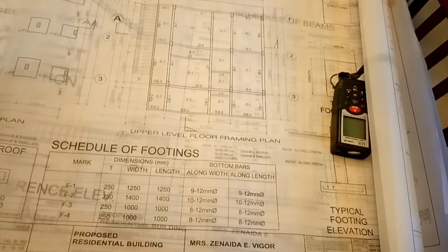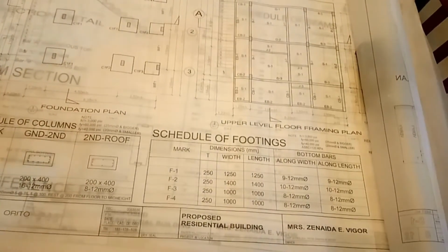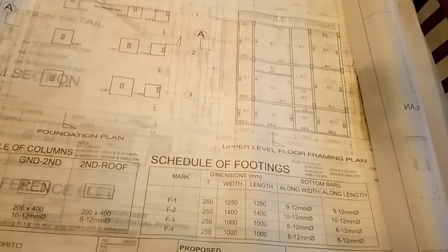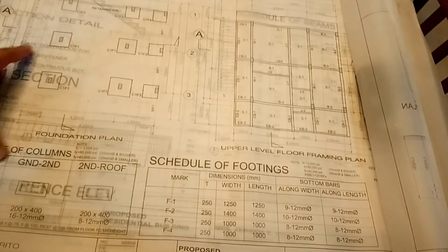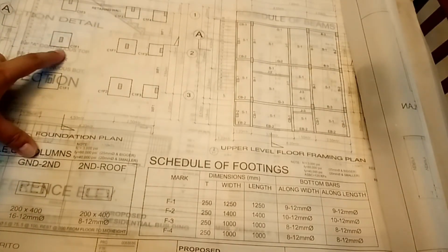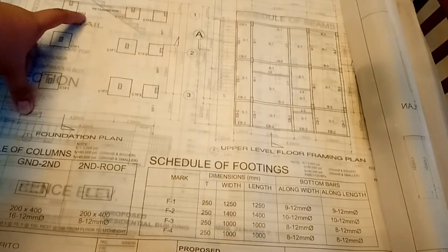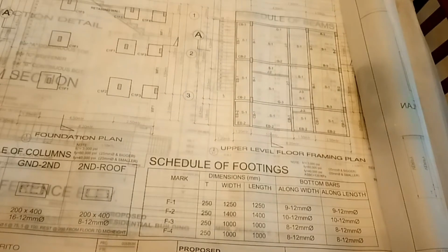Okay, so I hope that you learned something. So doing your foundation plan is not really that complicated. All you have to do is follow some basic principles, like what I've discussed earlier, especially in the designation of the structural components or elements. Like for example, if you're going to use the same column size, then you're going to write only C1, then F for the footing if it's different. So C1 F3, C1 F1, C1 F1. Okay, so the concept is quite easy to understand.